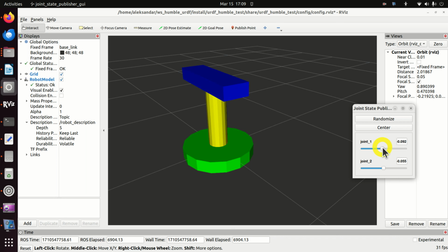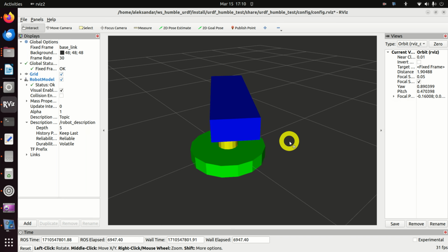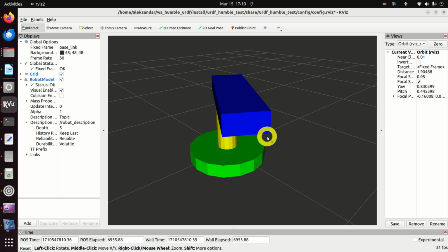In this ROS2 lesson, you will learn the basics of URDF modeling in ROS2. URDF is an abbreviation for Unified Robotics Description Format. This is a file format that's used to specify the geometry and model of robots in ROS2. Also, you will learn how to write launch files in ROS2 for displaying the URDF models. Besides this, you will also learn how to display the robot model in RViz.